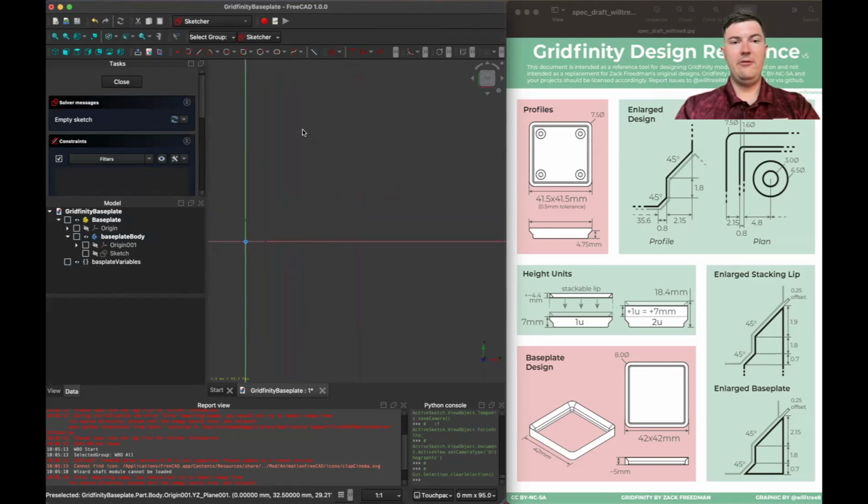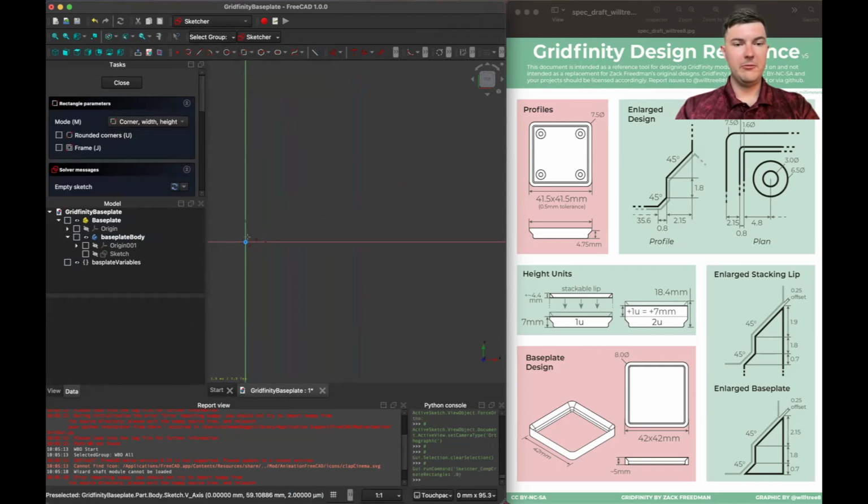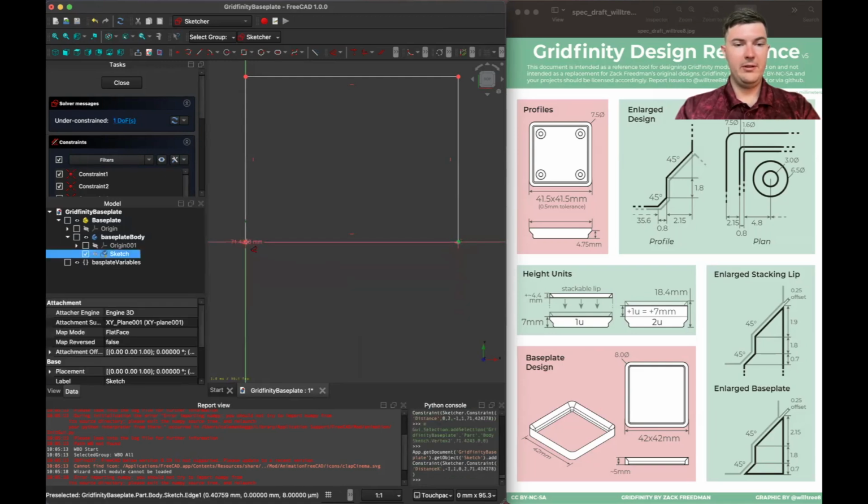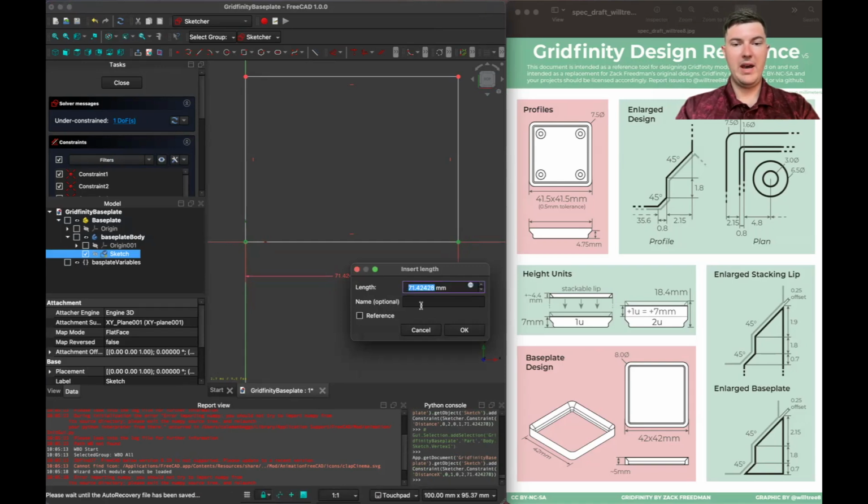And for this outer body, what I'm going to do is create a 2-corner rectangle. And I don't actually want that to be a rounded rectangle yet. I'm going to implement the fillets myself. So here we have it. There's our rectangle. And we're basically going to dimension this rectangle exactly the same as we dimensioned the outside of our Gridfinity box pad last time.